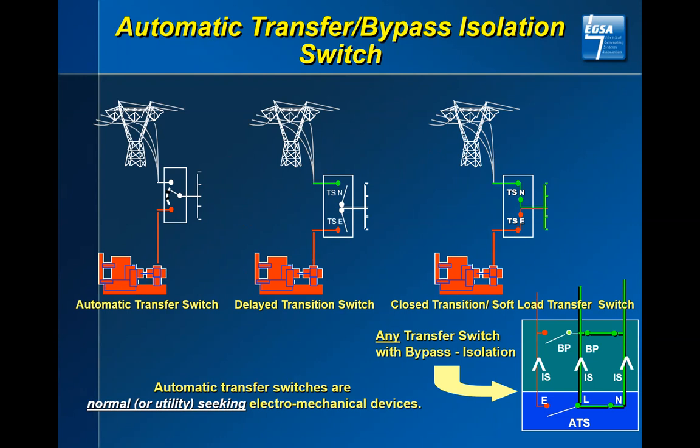And once you hit that demand charge, you may be locked into it for a complete year. So that's what you need to be aware of. Soft load switches are still available. If it's a specific application, contact the manufacturer and see what they can offer you. I will tell you though, if you're going to put in a soft load transfer switch, the utility company must be contacted. You have to know what their requirements are.